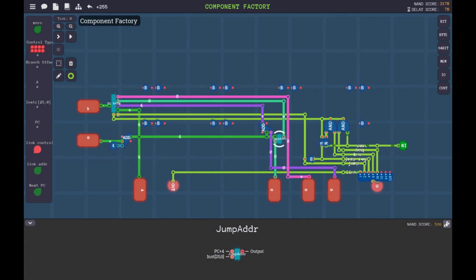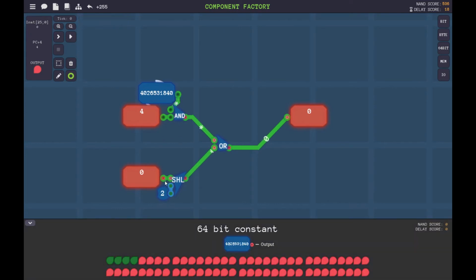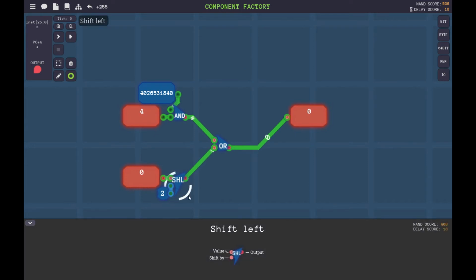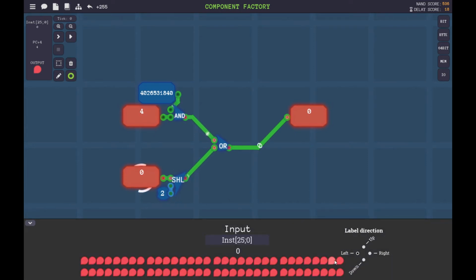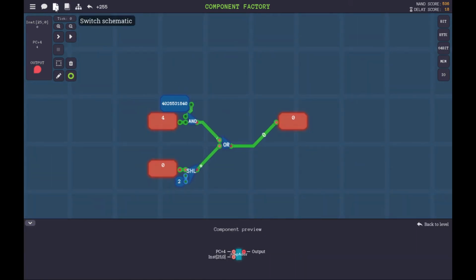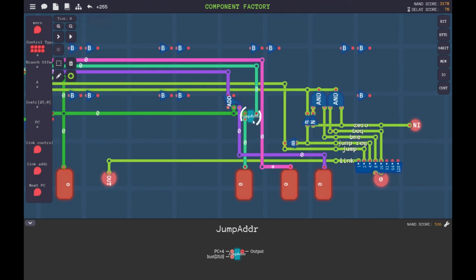This little unit is a very simple one. So this one takes the program counter plus 4, ANDs it with this, so this grabs the top 4 bits of the address of that instruction. Then it takes the 26-bit address immediate from the J-type instruction, shifts it left 2 bits, so this way we're moving zeros into these 2 bits down here, and moving the value that was originally there up. And so that way we can get those semantics of sticking 2 bits of zeros on the bottom, and then we OR those things together, and that gives us the output, which is the address that we should jump to. So this one's very, very simple, just a little bit of bit manipulation.